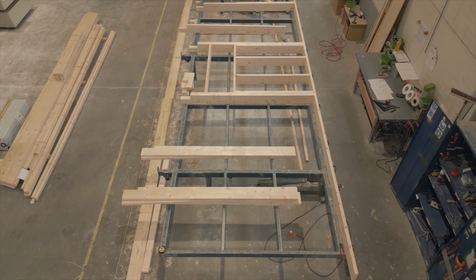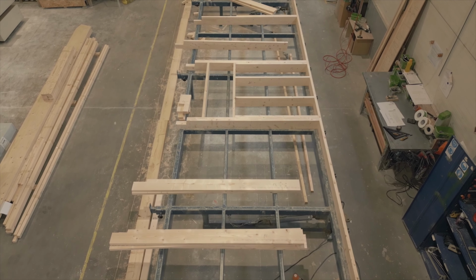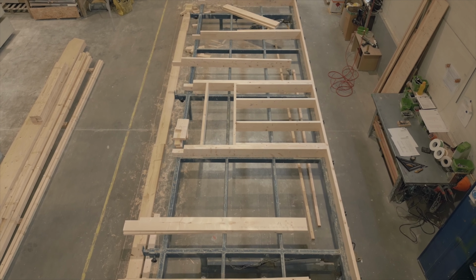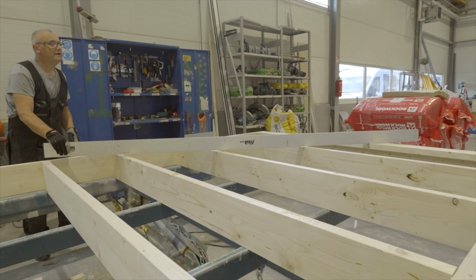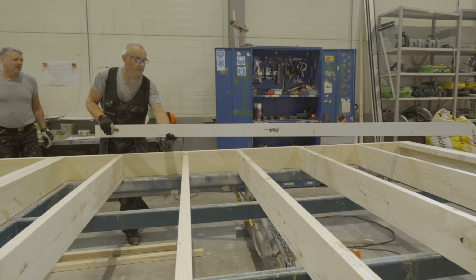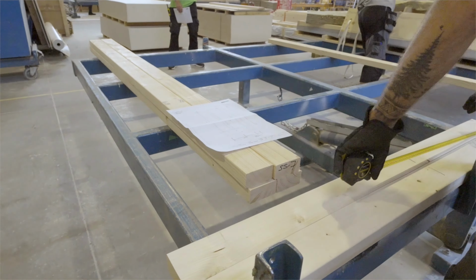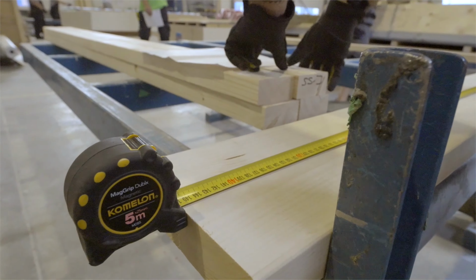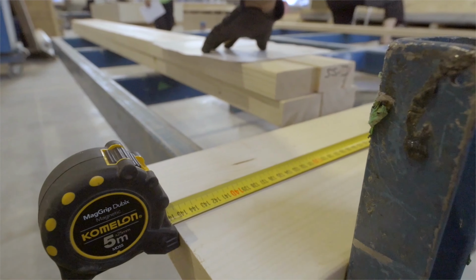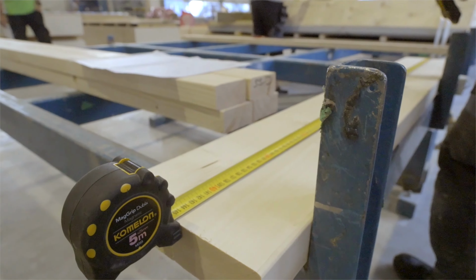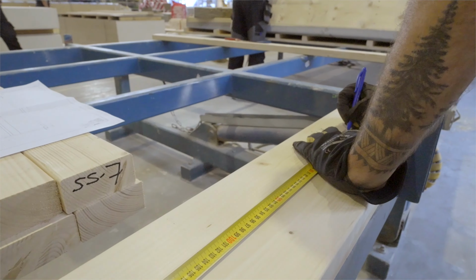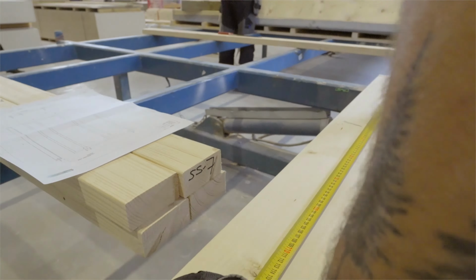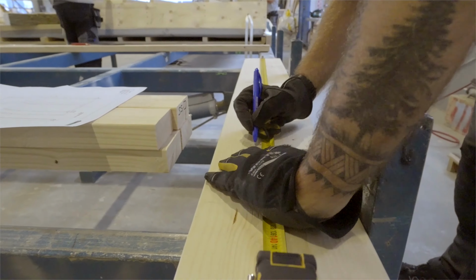The pre-cut parts shall be placed on the worktop in the position shown on the drawing and according to the specification. With the straight edge, the flatness of the beams must be checked. The frame studs must be positioned between the webs in fixed locations. To do this, pencil marks must be made in the correct places. If the locations of the wall frame studs have not been previously marked, then this must be done manually.